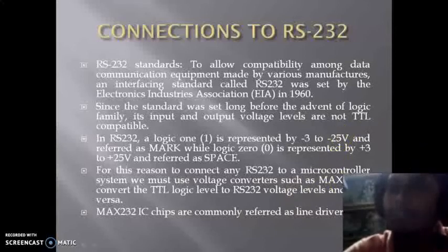So we have to connect a converter like the MAX232 so that the microcontroller can be connected with the RS232 standards. The MAX232 converts TTL logic levels to RS232 voltage levels and vice versa.